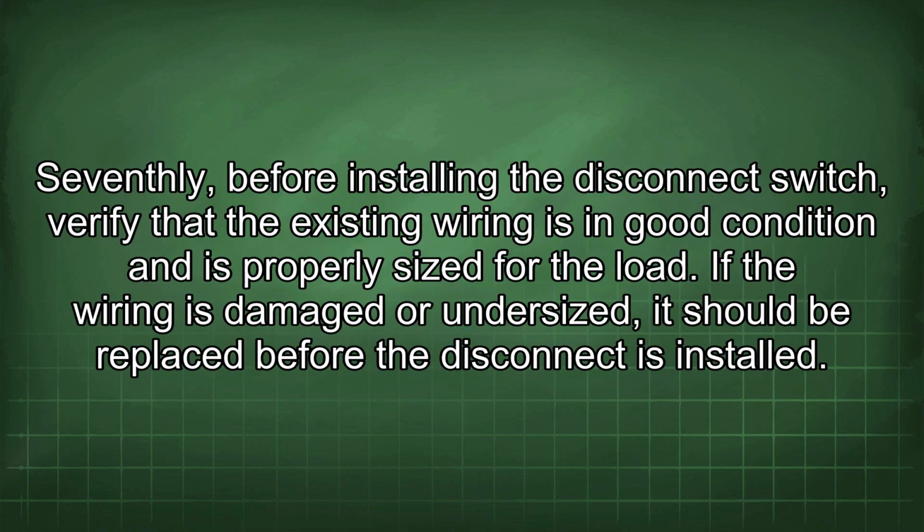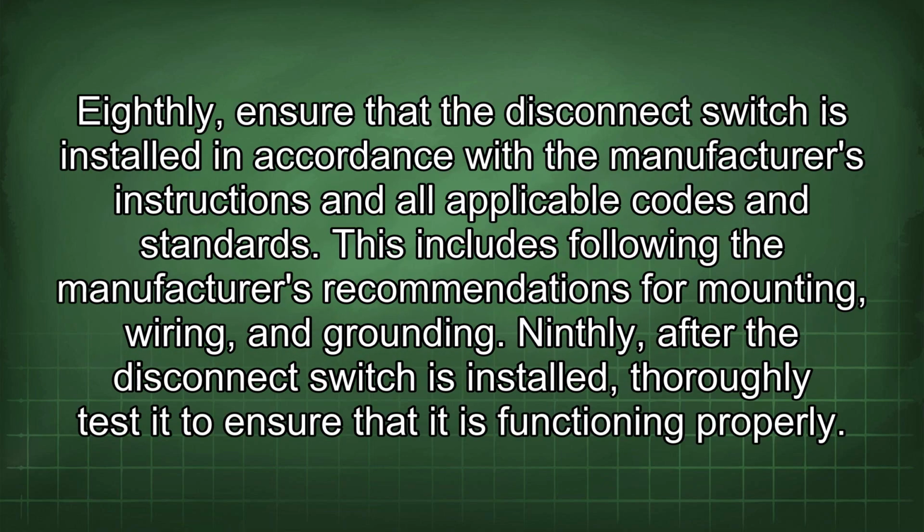Seventhly, before installing the disconnect switch, verify that the existing wiring is in good condition and is properly sized for the load. If the wiring is damaged or undersized, it should be replaced before the disconnect is installed. Eighthly, ensure that the disconnect switch is installed in accordance with the manufacturer's instructions and all applicable codes and standards. This includes following the manufacturer's recommendations for mounting, wiring, and grounding.